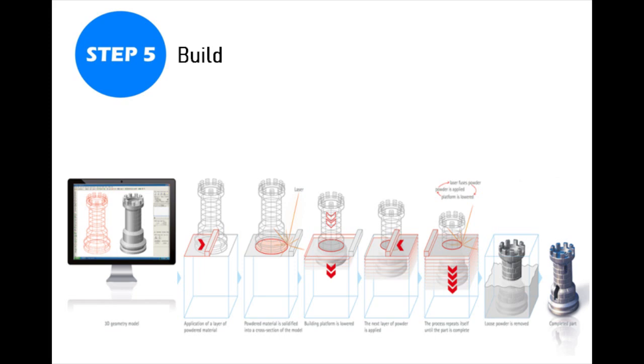All the additive manufacturing machines will have a similar sequence of layer control using a height adjustable platform, material deposition and layer cross-section formation. Some machines will also combine the material deposition and layer formation simultaneously, while others will separate them. All machines will repeat the process until either the build is complete or there is no source material remaining. In either case, the machine will alert the user to take action.